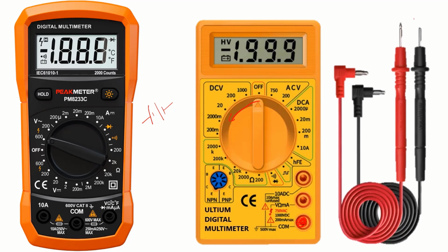the multimeter is connected normally, so it should be connected to the COM port and to the V ohm milliampere port. So what you do is you take one of the terminals of your meter, you connect on one side, you take the other terminal, you connect on this side. Get it? So it should be something like that. So here you have your voltmeter.